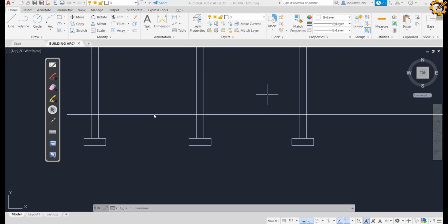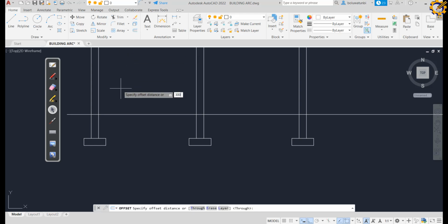Now this line here is my natural ground level, NGL. So from that NGL now I will start doing my floor constituents. So for our floor, all the area under this natural ground level is our soil. So we don't need to draw anything for soil any longer. So the only thing we are going to show now is what? Hardcore and what? And concrete. Now our hardcore, let us take our hardcore to be a thickness of 300 mm. Normally we ought to be given the standard, but the man won't give you, so I expect you to improvise. So I'm going to use 300 mm for my hardcore.